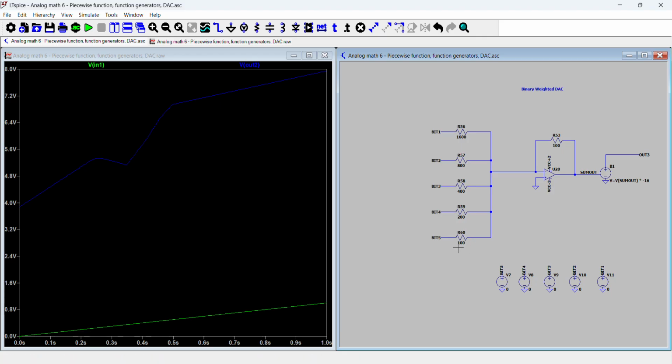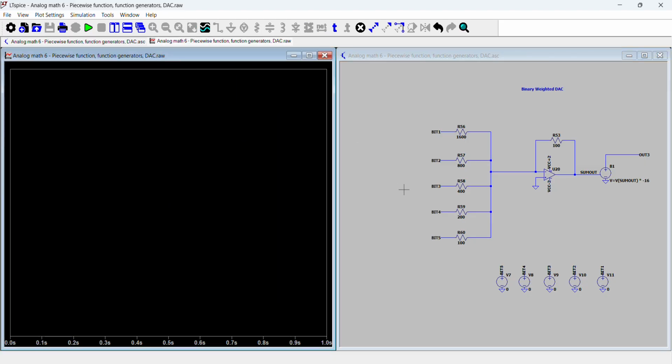a 2x resistor on the binary output side for every bit that you want represented. So, for example, for the fifth bit, the bit that is the largest in this case, I have 100 ohms of resistance, and then 200, which represents the fourth bit, etc., etc.